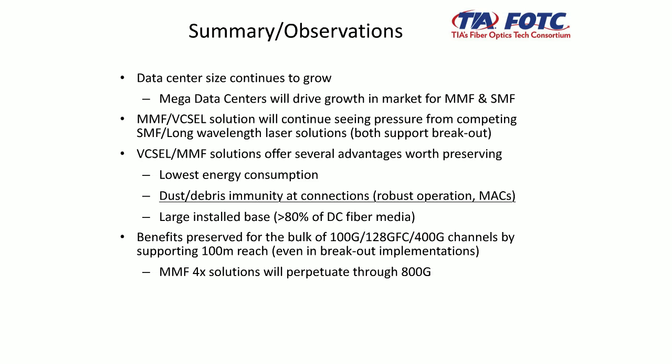The good side of multimode is not only does it enjoy the largest base right now, it's not the fastest growing, PSM4 is, with single-mode, but it is the lowest energy consumption. VCSEL devices take a lot less energy than laser devices. The big one that I underlined here, which may not seem like much, is dust and debris at connectors.